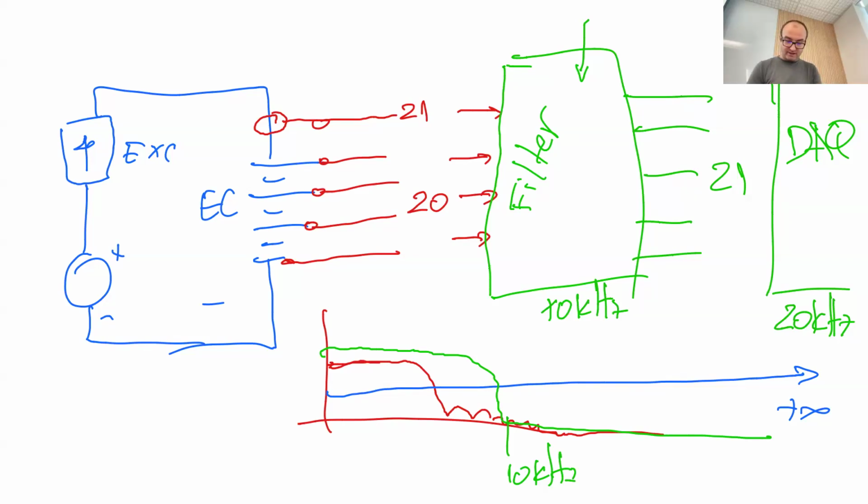Then it turned out that there is an additional limitation. The maximum data acquisition rate that we can do here is 100 kilohertz, which means that the maximum frequency that we are going to see is 50 kilohertz. So what I have to do now is redesign the filters from 10 to 50 and just reconnect new filters, and everything will be corrected accordingly.